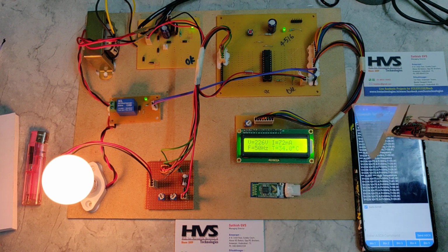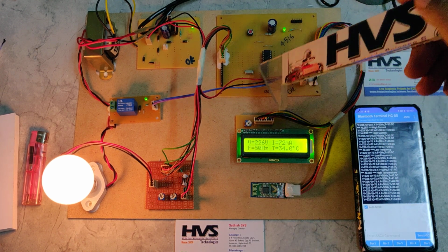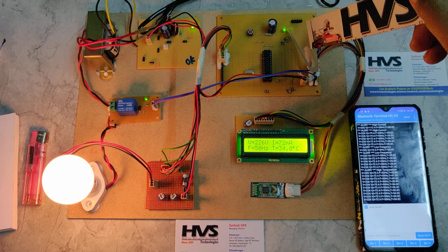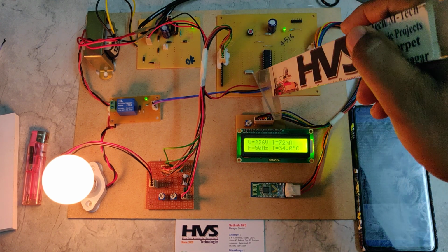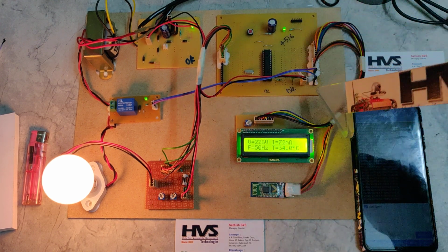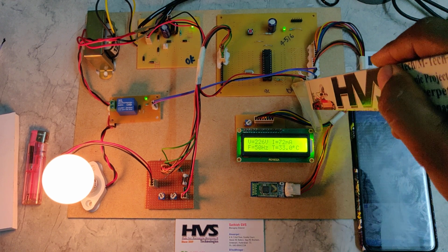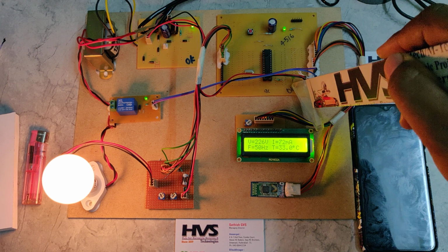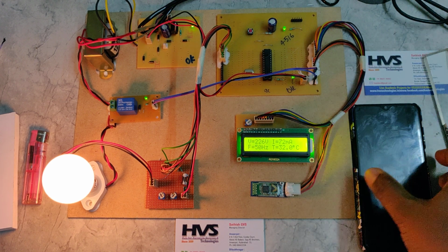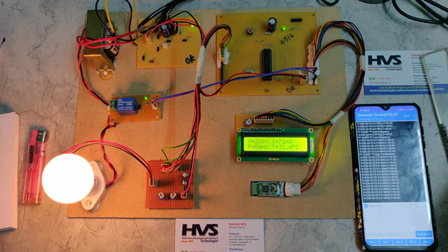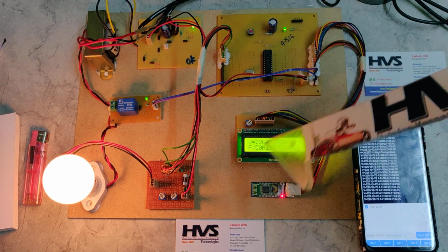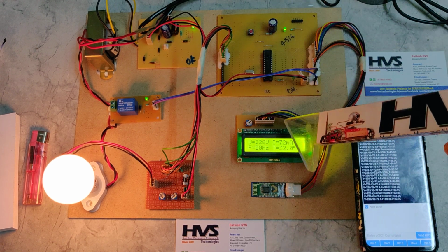In this manner, we get the substation, that is, the feeder parameters of voltage, current, temperature along with frequency measured. Coming to this motherboard, this is the reset switch, this one is the power LED indication, there is a crystal oscillator of 20 megahertz, and this one is a programmable LED indication. It blinks for every data sent to the Bluetooth mobile phone. And we interface these sensors and input output modules.